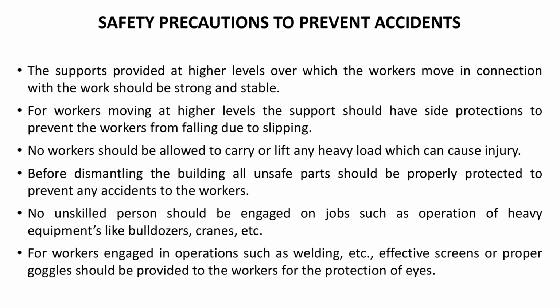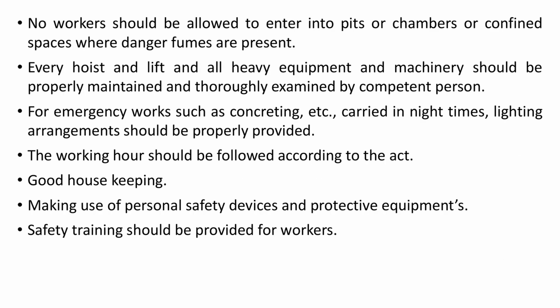No unskilled person should be engaged on jobs such as operation of heavy equipment like bulldozers, cranes, etc. For workers engaged in operations such as welding, effective screens or proper goggles should be provided for the protection of eyes. No workers should be allowed to enter into pits or chambers or confined spaces where dangerous fumes are present.